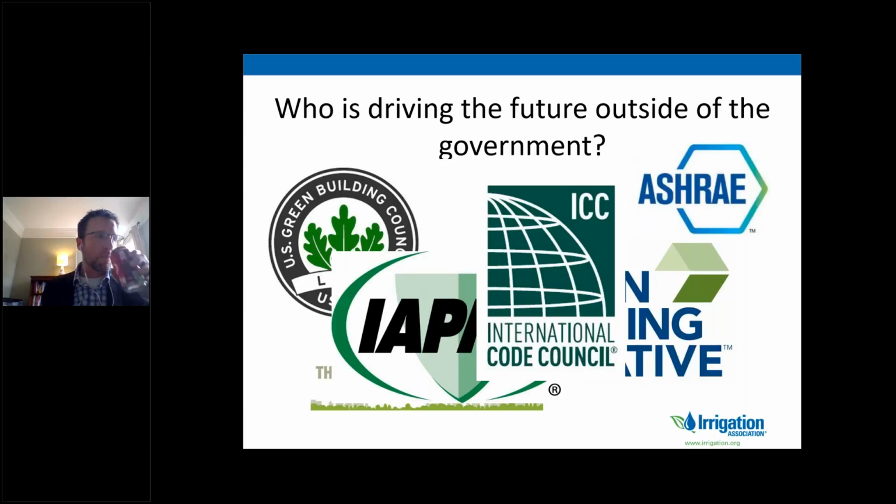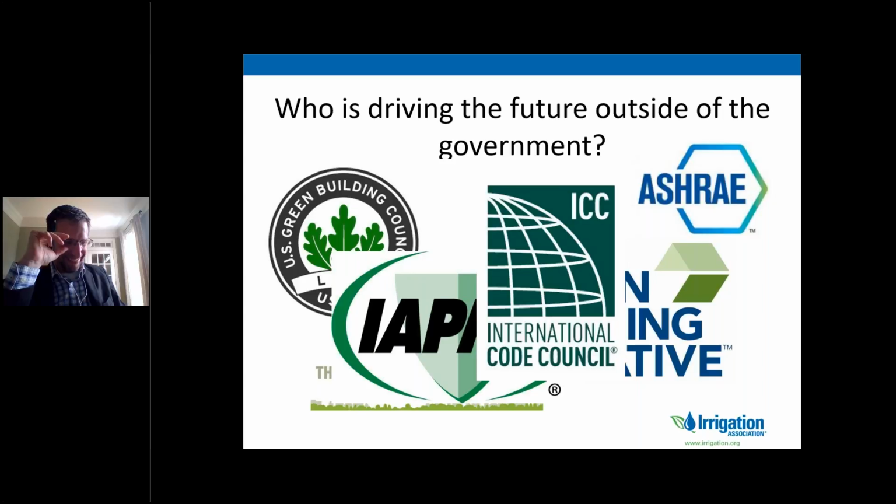and for years had in there as an option the Model Water Efficient Landscape Ordinance. However, it's no longer a model. I'm suggesting that maybe M has now changed to mandatory because it's now in the building code that all new construction will be following this water budget approach to creating the landscape and how much water will be available. So now that's into the building code. That means it's going to be revisited every 3 years by state statute. So they've been doing that.